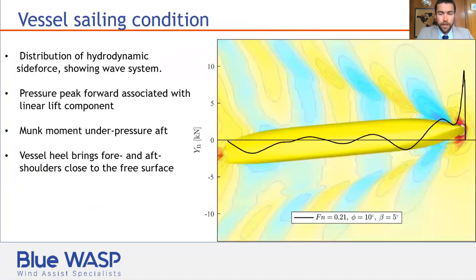So what happens when a large sailboat moves through the water? There has to be a balance in the transverse direction. So there will be a heeling force next to an aerodynamic thrust. And then as a result, the ship will adopt a heeling angle and a leeway angle. So here you have 10 degrees heel in the image and 5 degrees leeway. The viewpoint, by the way, is from beneath the ship. So that's the normal ship maneuvering coordinates or hydromechanic coordinates.